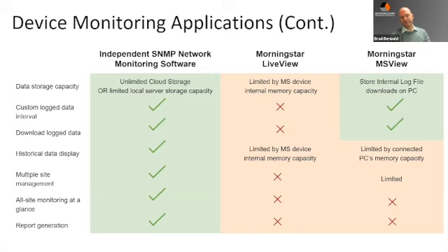And also, since it's being managed in the cloud, instead of you checking on the site and logging in to see how things are going, the cloud will actually monitor the data and alert you based on pre-configured notifications, like a low battery voltage or a site has gone down or excessive load draw or temperature impacts. Things of that nature will proactively come to you, because when you reach hundreds or even thousands of sites, that's really the only way you can monitor something of that scale.